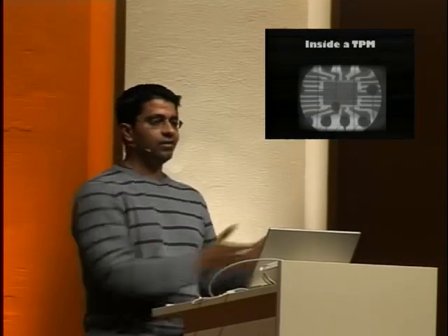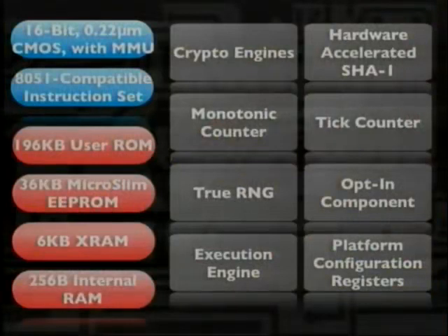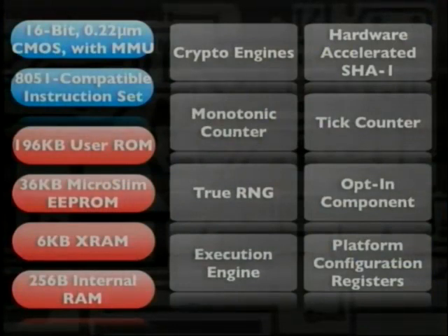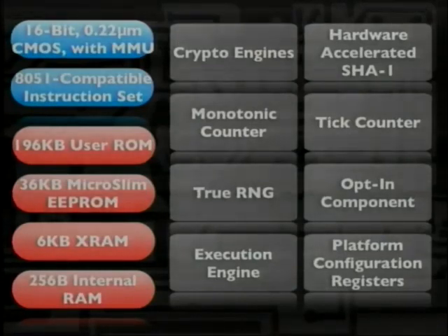In fact, if you see what chipset is inside and what embedded stuff it's running, it's running the same stuff a smart card would, except that the company who manufactures this also makes the smart card, so there's a small production difference. But it's running a lot of the same things a smart card would. Stuff like this. So there's a microcontroller. Which thing doesn't have a microcontroller? There are a few types of memory, both volatile and non-volatile, and some functional components, lots of cryptographic stuff, some of which it exports, some of which it does not export.